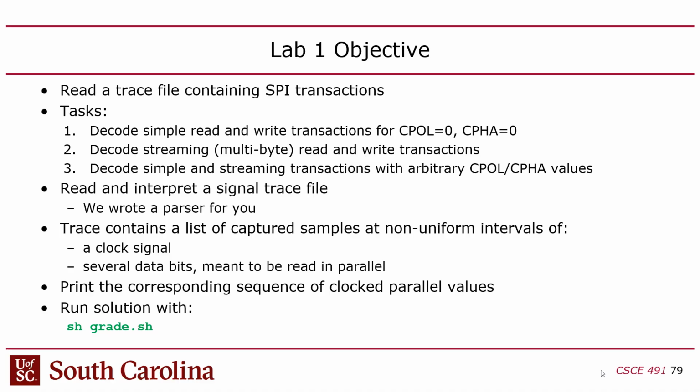So the idea is that we want to develop a software decoder for SPI. So SPI is basically based on a parallel to serial conversion, right? You're taking parallel data, serializing it into single bits, sending those bits across, and then there's some protocol stuff you have to worry about when to read and write the bits. So we're going to give you a trace file, which is like what you would get if you recorded a recording from a logic analyzer or an oscilloscope. It's like signal voltages, right? You're going to read that file and then convert it into English prose describing what the transaction is doing, right?